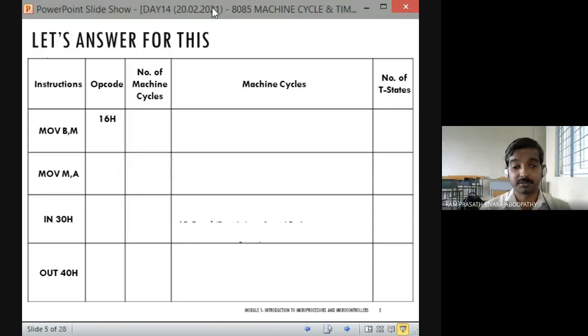What does M refer to? Yes, move data from register pair. No. It does copy the data from memory only. Yes, very good. The memory pointed by HL register pair. Okay, fine. Kindly correct it. Your intention is correct, the register pair is involved. HL register pair is involved. Fine. Whenever I say M, you should immediately think about one register pair, HL.